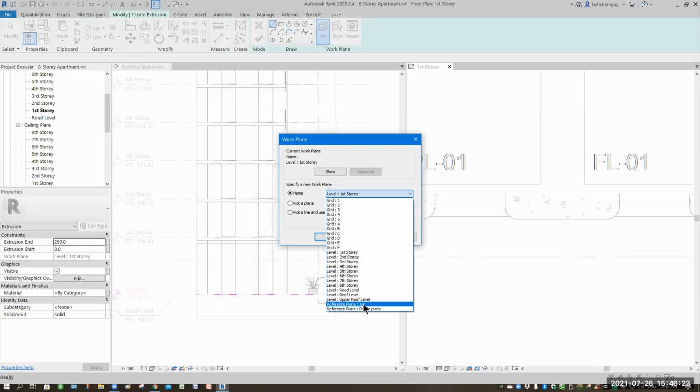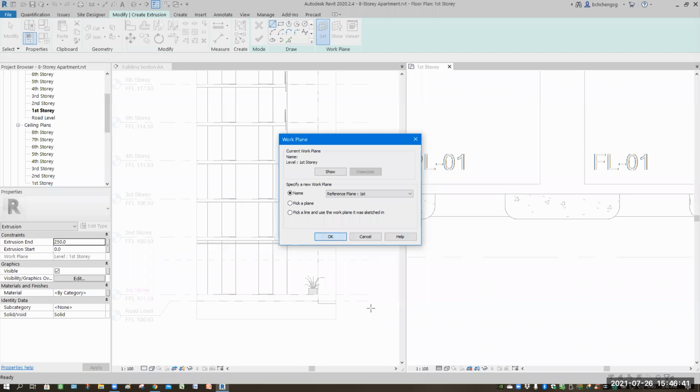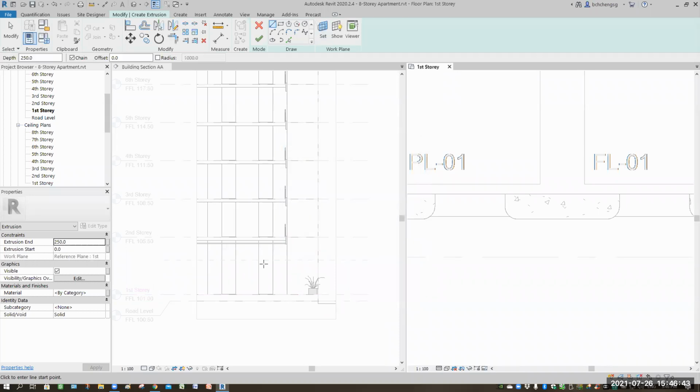But for some reference planes, maybe for tracking purposes, you may want to give a name, so it's easy to track. If I never give one, then I can use pick plane to define that. Okay, so now I select this. They automatically base on that as a reference. Now you do the sketches.